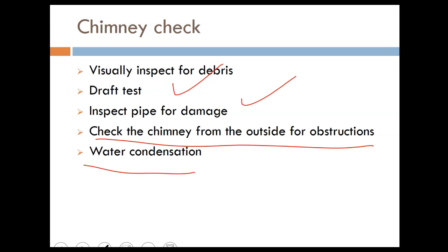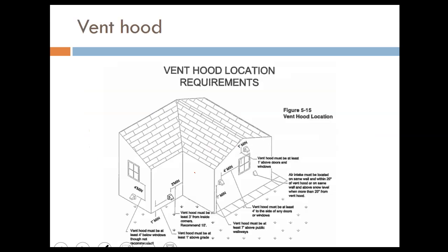So you have to go check the chamber and check the combustion and make sure it is at least 450 degrees Fahrenheit. If it cools off, you're gonna have condensation and you're gonna have to burn it a little bit higher, and probably you have to consult with the manufacturer to see what to do to increase the temperature of that chamber. Here are some guidelines about where you end these vents if you don't have a chimney.